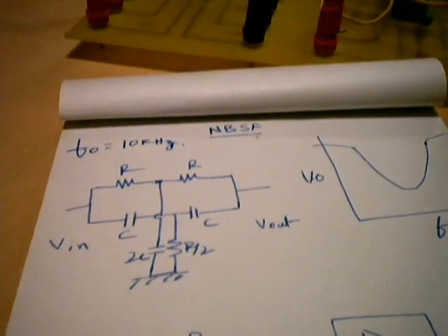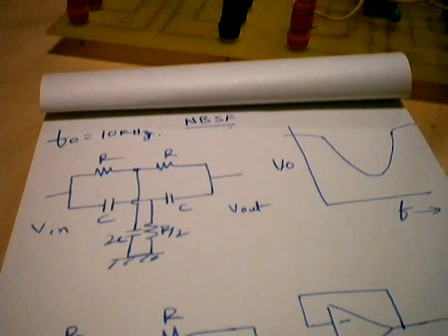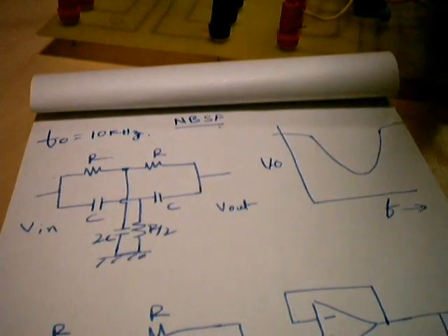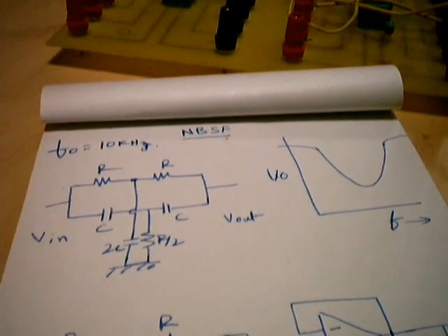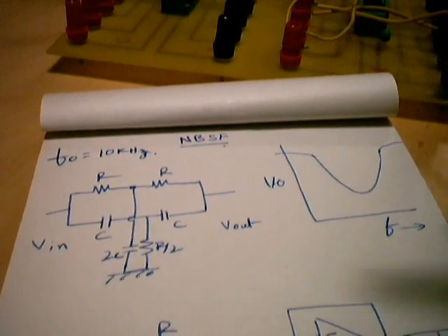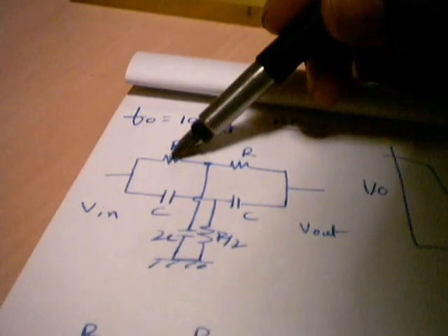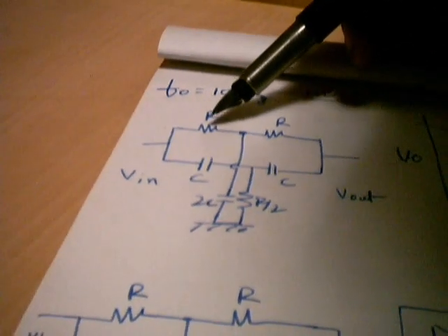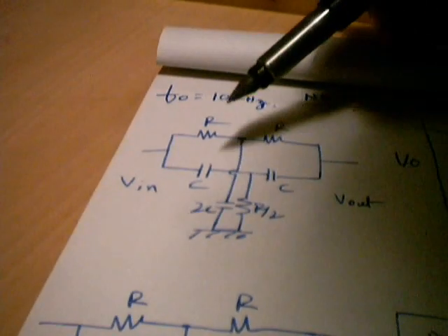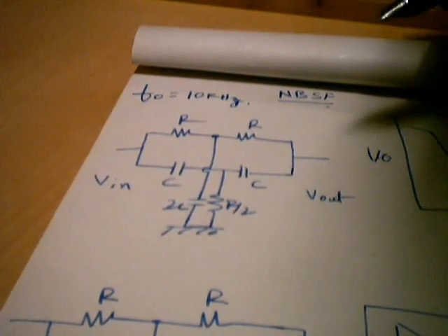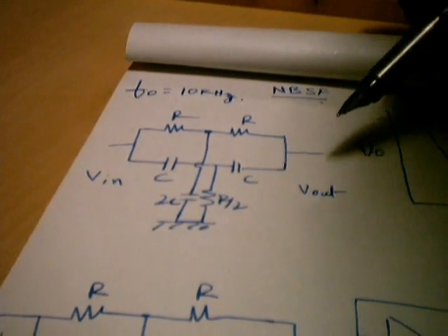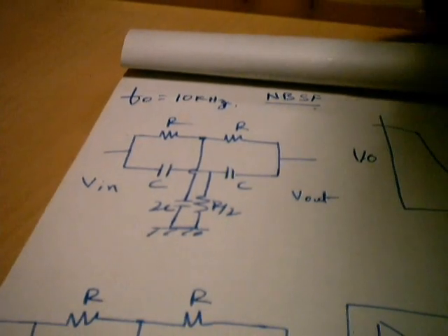We'll see the working of the narrow band stop filter. Here we are utilizing a twin-T circuit. The basic circuit diagram of this is a twin-T circuit consisting of one T comprising R, R and 2C. The other T circuit is C, C and R by 2. So here itself we'll get the narrow band stop action.